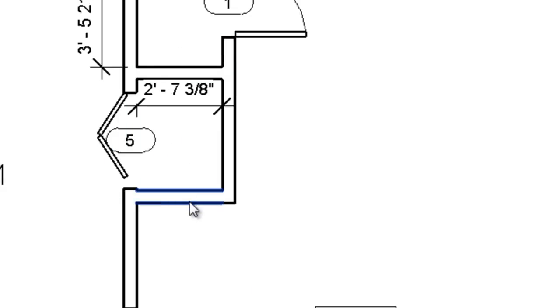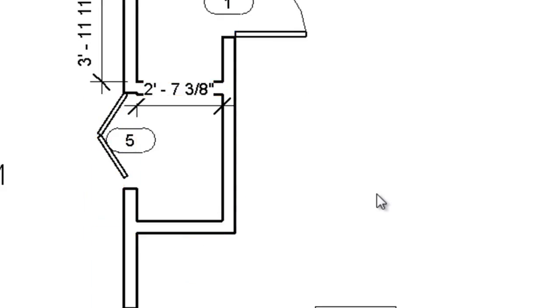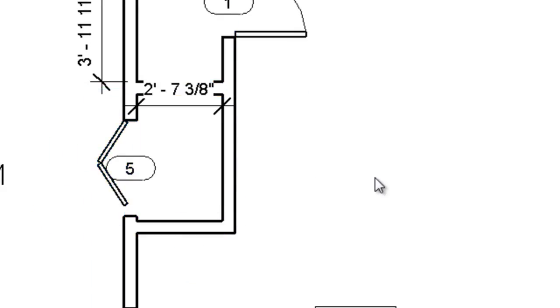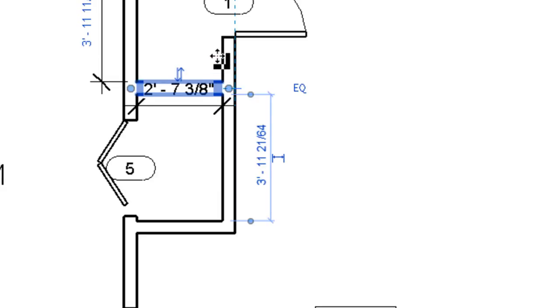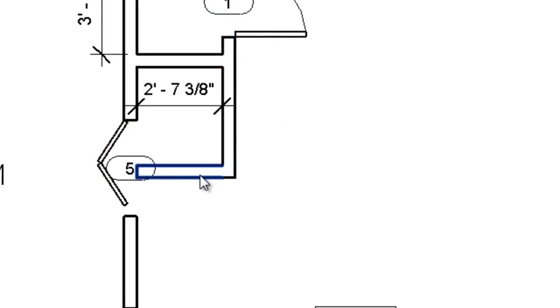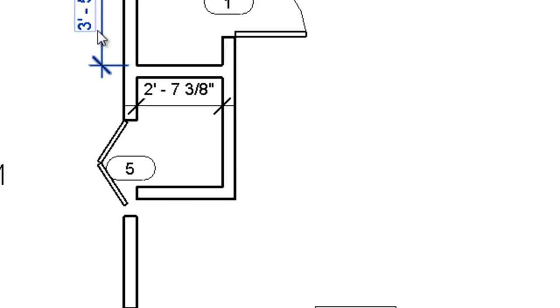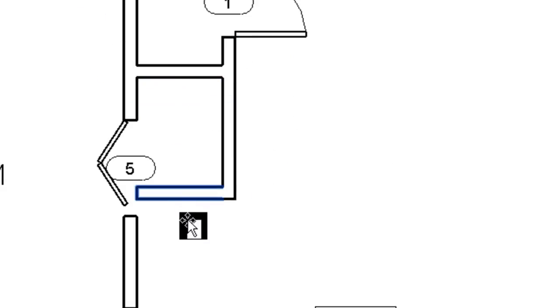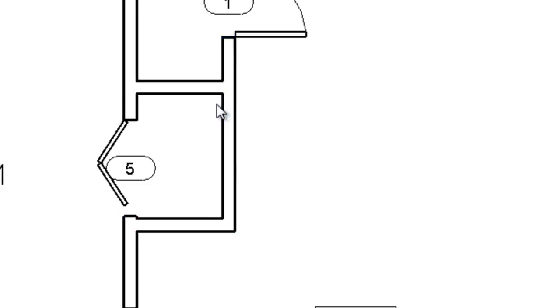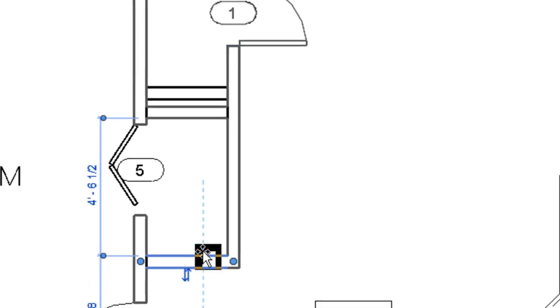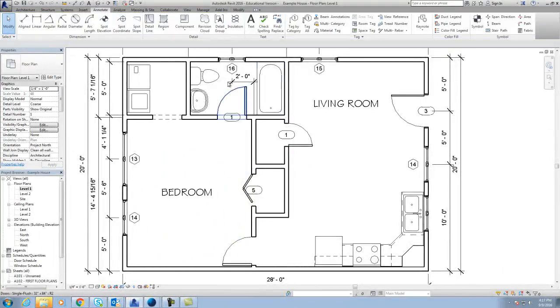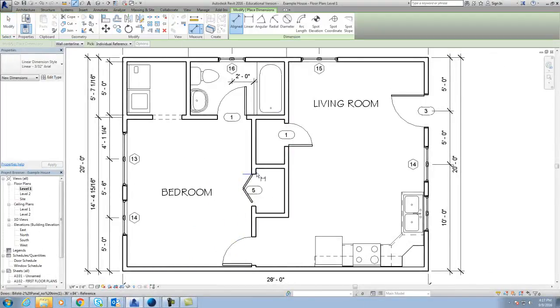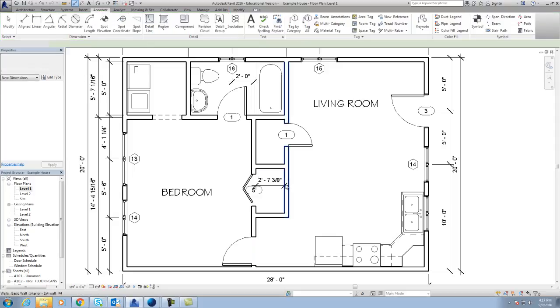Closet. Now this closet needs to be a little bit larger. So those walls are locked. Now we start dealing with this closet here. You got to make sure that a closet, according to FHA rules, has to be at least 2 foot inside so that you can have space for your clothes, and that's good.